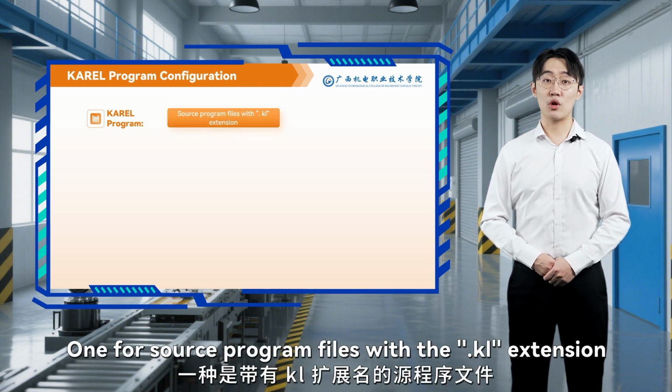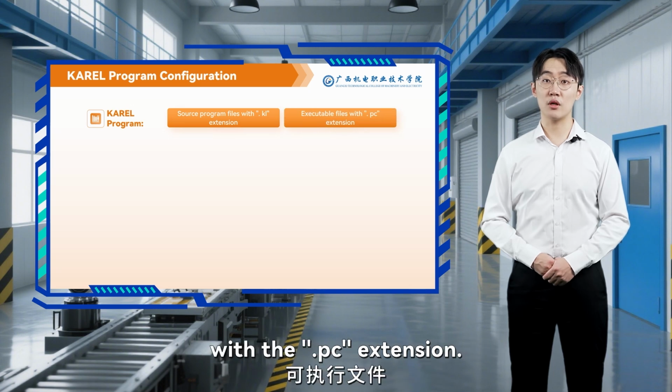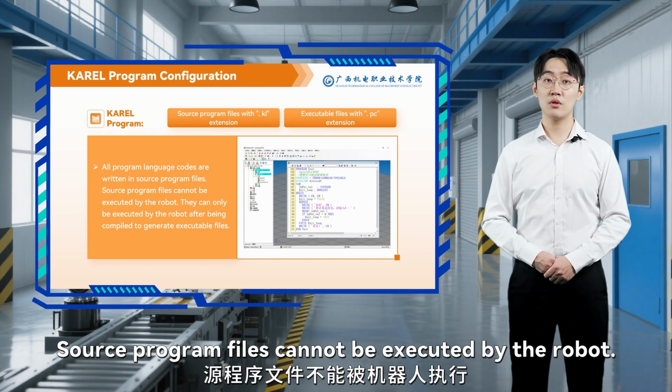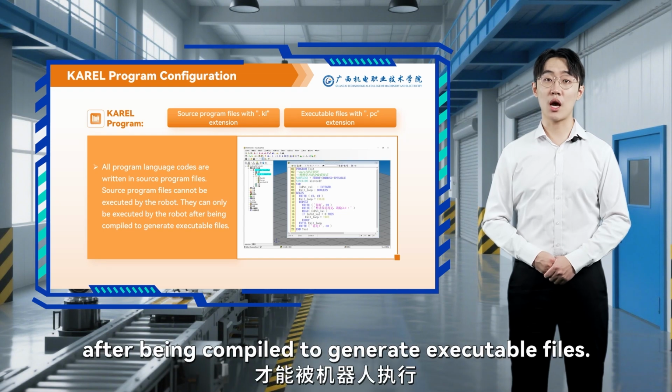One is the source program file with the .KL extension, and the other is the executable file with the .PC extension. All program language code is written in source program files. Source program files cannot be executed by the robot. They can only be executed by the robot after being compiled to generate executable files.